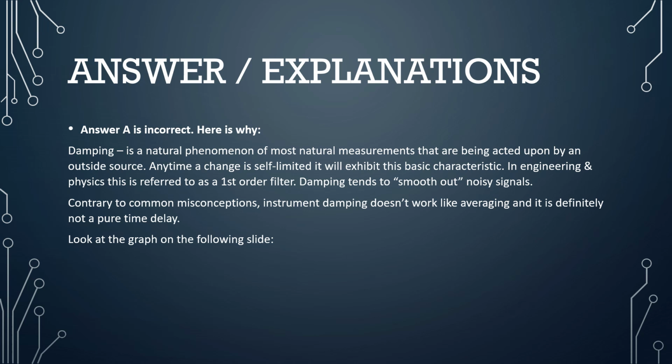In engineering and physics, this is referred to as a first-order filter. Damping tends to smooth out noisy signals. Contrary to common misconceptions about damping, instrument damping doesn't work like averaging at all, and it is definitely not a pure time delay, which is one of the most common gross misconceptions. We'll look at the graph on the following slide to explain that a bit more.